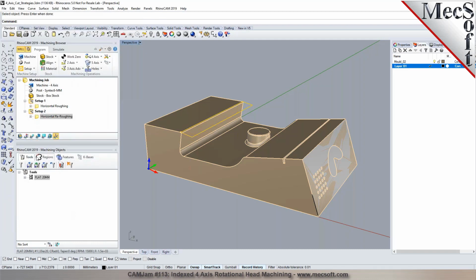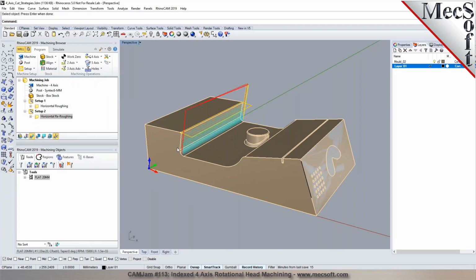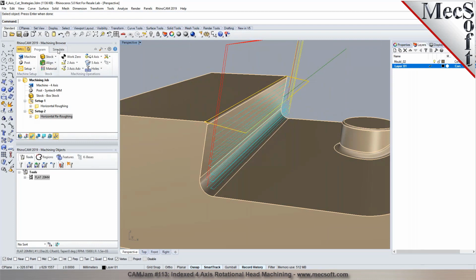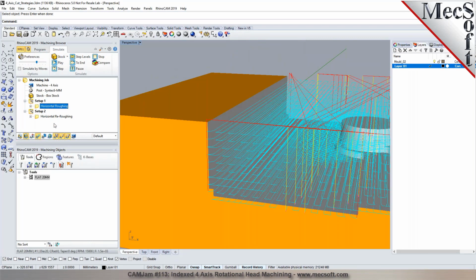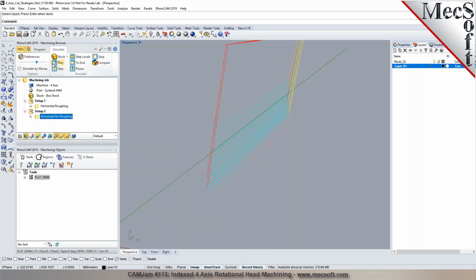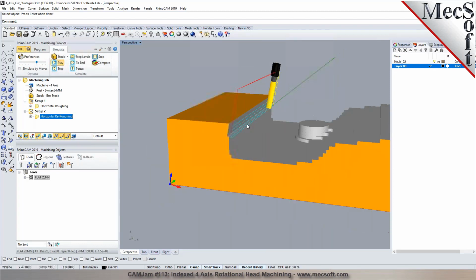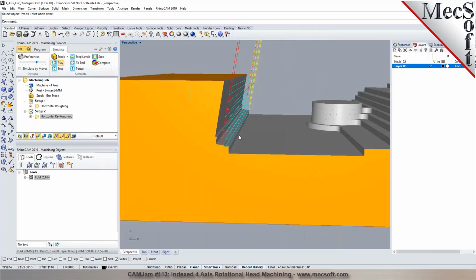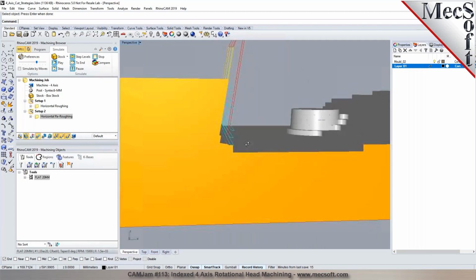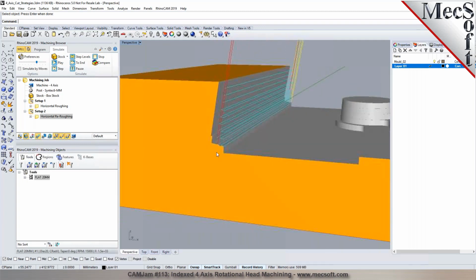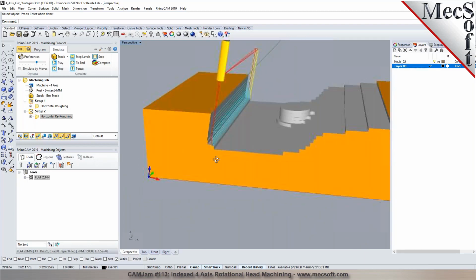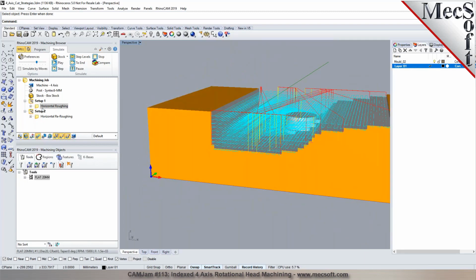So in this process, the re-roughing actually looks at the in-process stock, which is the material that's being left from the previous step. So even though you machined it looking down from the top, now you have tilted it. So it takes into account the in-process stock, and it's only clearing material. You can see there's more material down as you're cutting down in levels. And when we post it, we'll compute the angles and output it for going from setup 1 to setup 2.